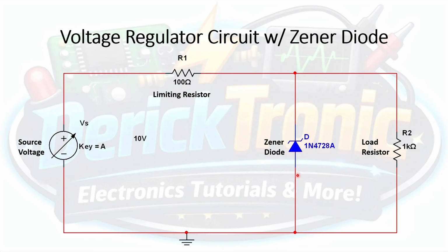Its anode is connected to ground, while its cathode here at the top is connected to the positive terminal of the voltage source. Now, what will happen in this demo is that we will first set the voltage source to a low value, let's say 1 volt. Then we will gradually increase it, let's say 2, 3, 4, increments of 1 volt, up to 10 volts maybe. At each pass, we will be measuring two things in this circuit. First one is the load voltage, or the voltage across R2.